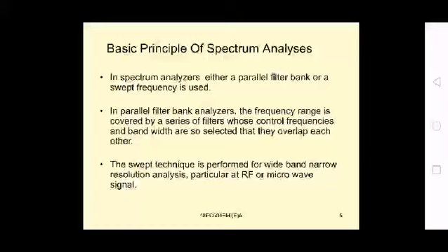For small frequencies, where the input has only audio frequency, we are going for the parallel filter bank technique, where we put a series of filters, and the entire frequency range is covered by the series of filters whose center frequencies and bandwidth are selected so that they overlap with each other. But the swept technique is performed for wideband narrow resolution analysis. It is done at RF, radio frequency and microwave signal levels.